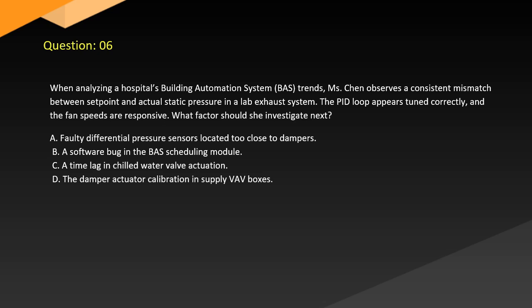Question 6. When analyzing a hospital's building automation system, BAS, trends, Ms. Chen observes a consistent mismatch between set point and actual static pressure in the lab exhaust system. The PID loop appears tuned correctly, and the fan speeds are responsive. What factor should she investigate next?